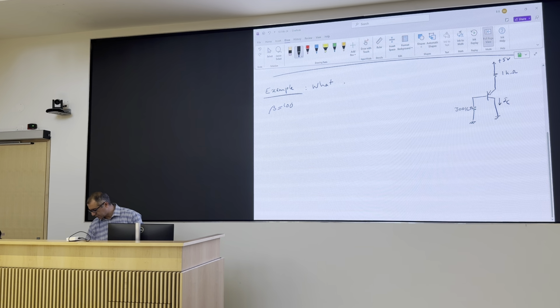Remember that you have two junctions, N here, N plus here, P here, right? For each junction, you have a depletion region. So you have a depletion region here, and a depletion region here, and then one at the bottom. In the depletion region, you have negative fixed charges here on the P side, and positive fixed charges on the N side, right?